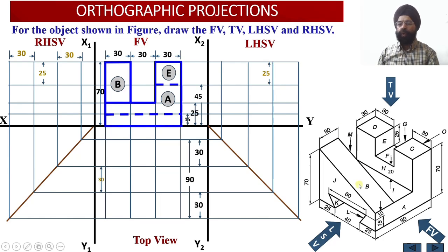Now we are going to move on to these edges. So corresponding to the slot which is available at the bottom, we have got 2 edges on the back side and 2 edges on the front side. Now let us plot the edges which are available on the rear side and the edges which are available on the front side corresponding to this angular slot which is available at the bottom of this particular solid. Now we know that these edges are not visible to the observer from the top, so they will be drawn as dotted line projections in the top view over here.